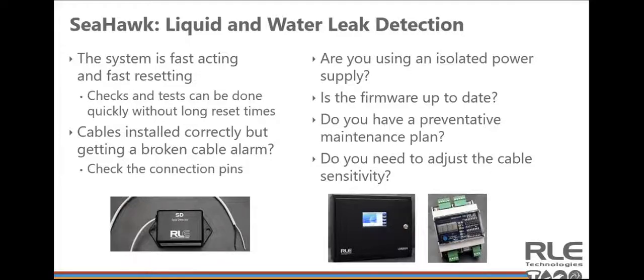And another thing I found is if you're in the data center and you're using a Seahawk leak detection cable, sometimes you run into space requirements where you can't put the cable the recommended 4 to 6 feet away from the discharge point of a CRAC or CRAH unit that has a humidification cycle in it. Keep in mind that if you do have to go closer, it's doable, but you do have to make some changes on the sensitivity of the cable. Otherwise, you'll get false alarms from condensation buildup on the cable.